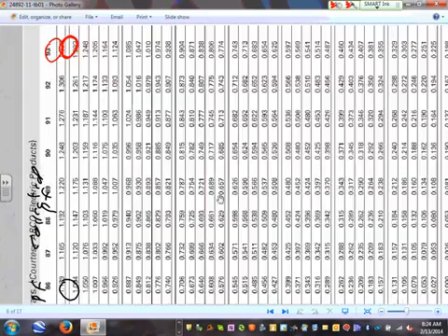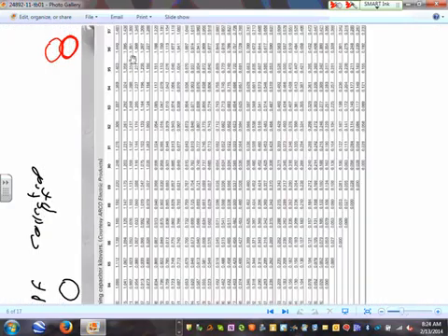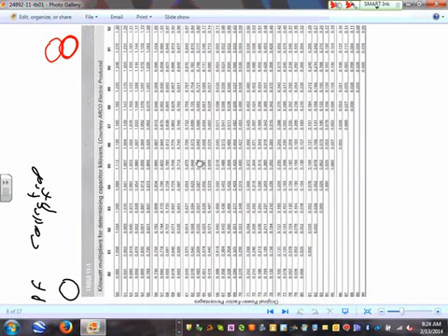The most important thing, guys, on the top side, is what you correct for. And this here is the original power factor. So on the test, when I tell you guys, go correct for a power factor of 90, and the original power factor was 60, this is corrected, this is original. So when I say go correct it, I'm going to go all the way up to here, and your multiplier M is going to be 0.849.